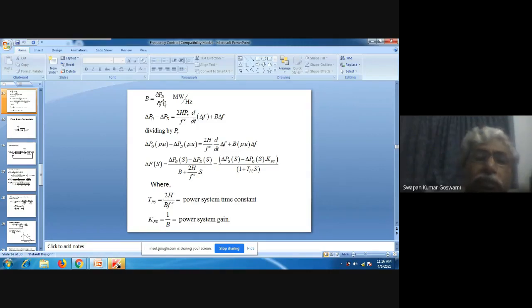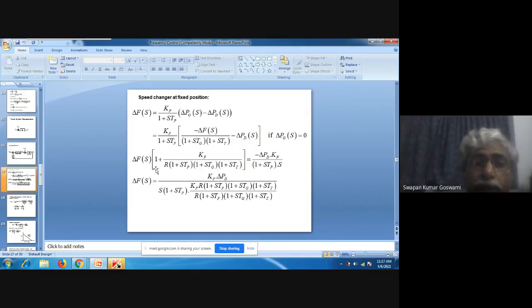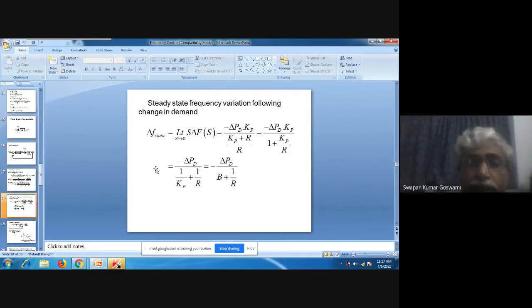With the reduction in frequency, demand of the existing load will decrease. That means existing loads will consume somewhat less power when the frequency decreases, and somewhat more power when the frequency is increased. This is how load actually responds to variation in frequency.